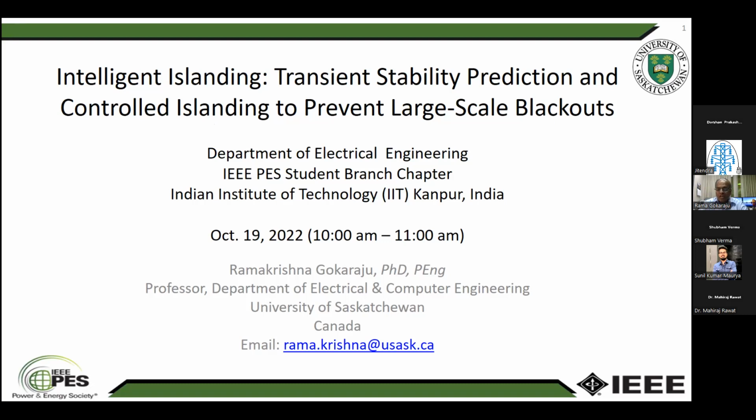Obviously, on a large system, if the generators are tripping and the loads are tripping, the whole system may collapse. So we want to do a controlled islanding if it is possible, so that we can create islands where there is a generation load balance, so that we can retain as much of the system as possible.